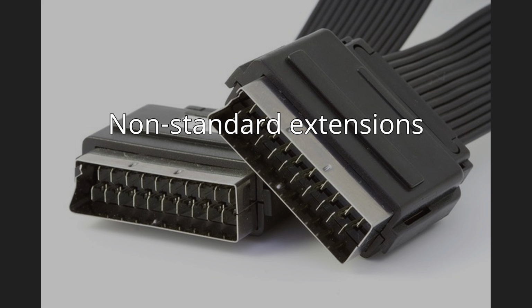Some manufacturers used the composite video connection as Y, while others used the green connection as Y. With the advent of HDMI, and because the connection was not standardized as S-video was and was limited to certain manufacturers, devices supporting high-definition over Scart with YPbPr became scarce, if not extinct.